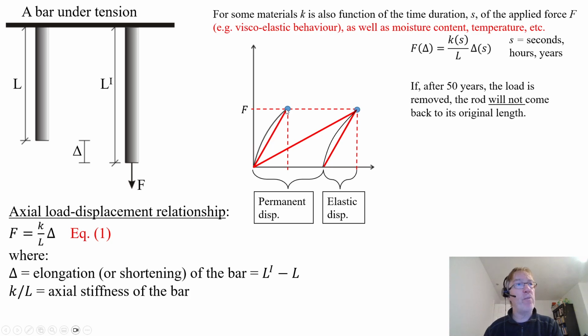But if we apply the load on, leave it for a period of time, say 50 years, we then take the load off, it will not go back to its original shape, it will not go back to there, but in fact you'll see some new permanent displacement taking place. Then you take the load off, put the load back on again instantly, and you'll have that elastic displacement there.